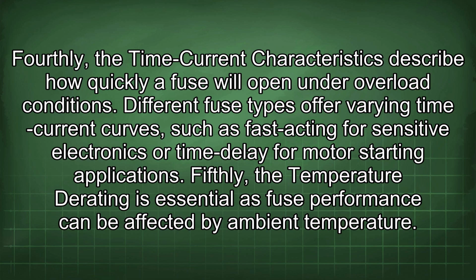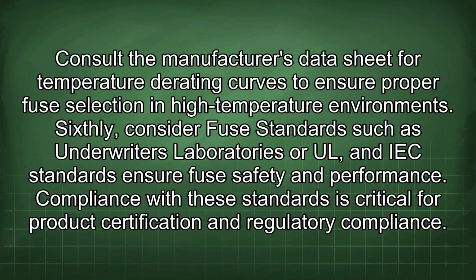Different fuse types offer varying time current curves, such as fast acting for sensitive electronics or time delay for motor starting applications. Fifthly, the temperature rating is essential as fuse performance can be affected by ambient temperature. Consult the manufacturer's datasheet for temperature rating curves to ensure proper fuse selection in high-temperature environments.